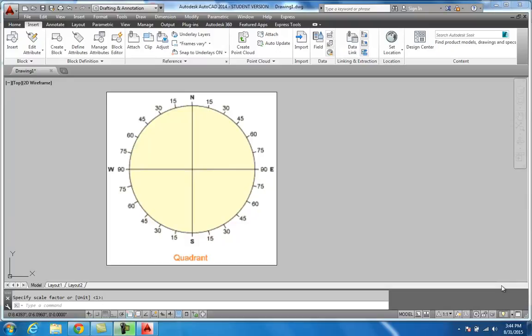Welcome back to week 3, and this week we've been able to do a couple of new things in creating lines. We did the direct line method, which we had to utilize ortho in the status bar, and we also got into polar coordinates, and that's whenever we had the length of the line and the angle, and we're able to use that data to draw in a line at a certain degree of an angle.